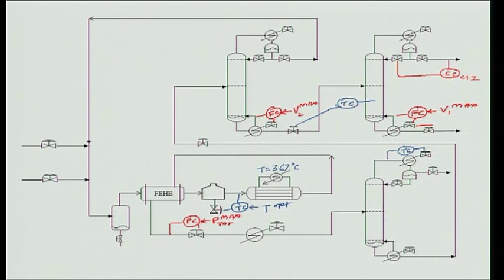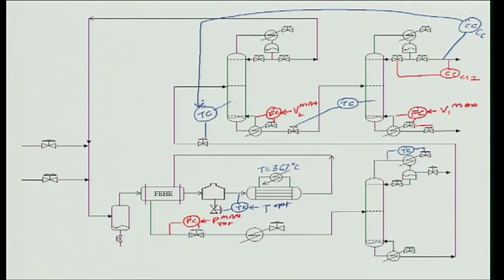I also need tight temperature control of the benzene leaking down the bottoms of the recycle column. However, its boil up is also at maximum, so I cannot manipulate the boil up. Similar logic, I control temperature using the feed to this column, and of course I have a benzene composition controller, composition of C6, and that composition controller is essentially setting this set point. So that takes care of economically important things.